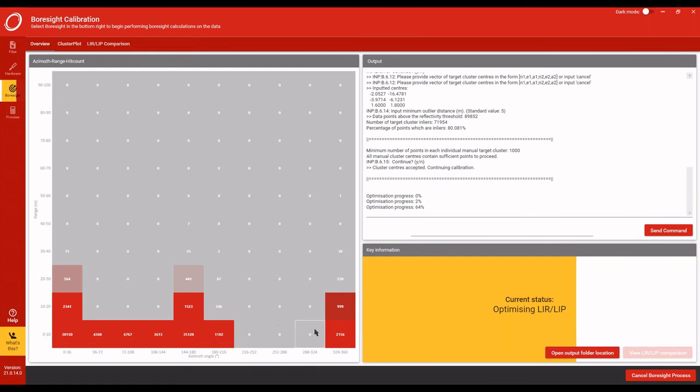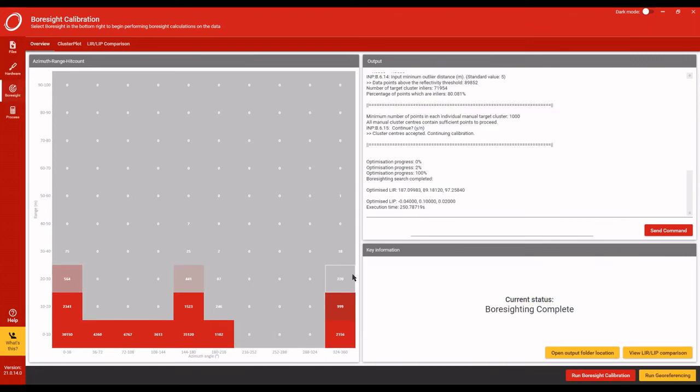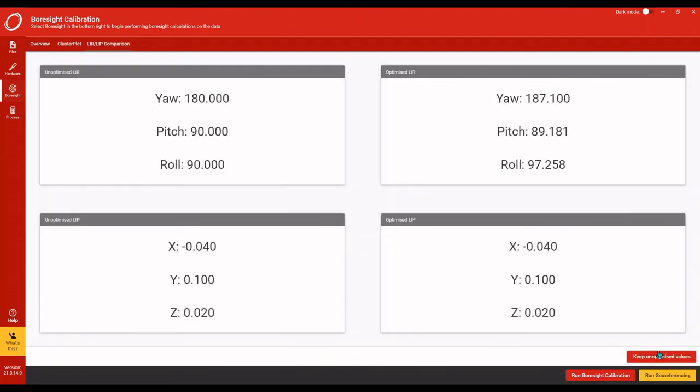And then at all the other angles, you can see it's getting hits around 0 to 20 and then 30 meters. And this is what you would aim to get. So you want to be viewing those targets from a range of typical angles and distances that you would expect to survey at.